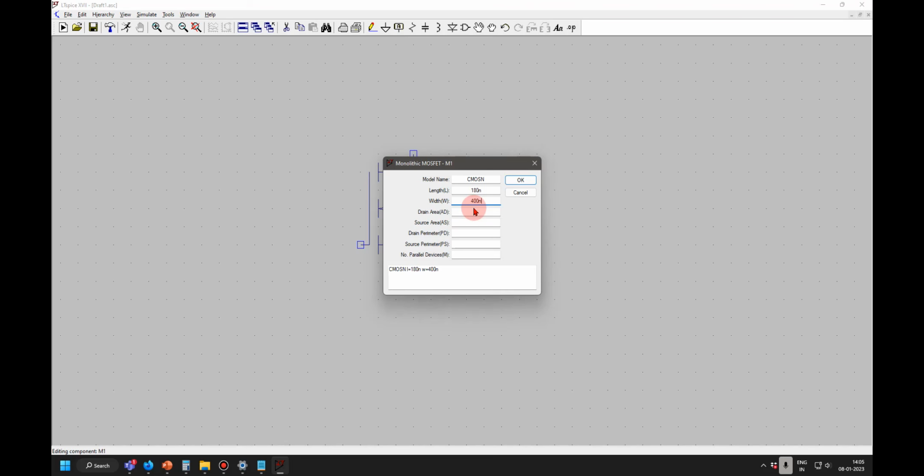Once a foundry gives the model, like the TSMC model, say I am using TSMC and designing a circuit, L and W are variables for me. I will use whatever length I want to optimize my design, and I will design a circuit. Having designed the circuit, I will make a layout out of it and send it to the foundry. The foundry will fabricate it based on the L and W which I have specified.